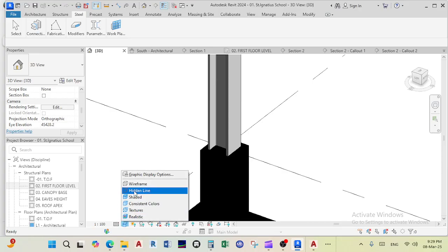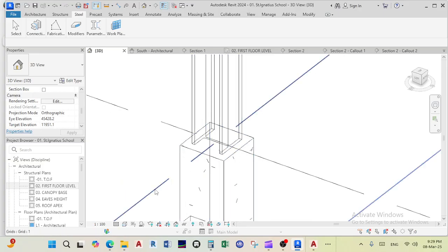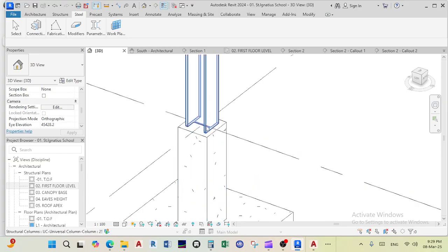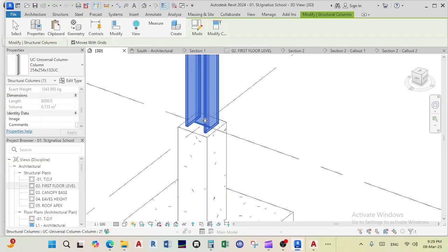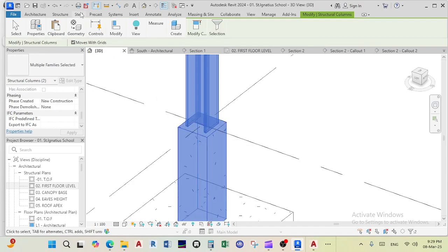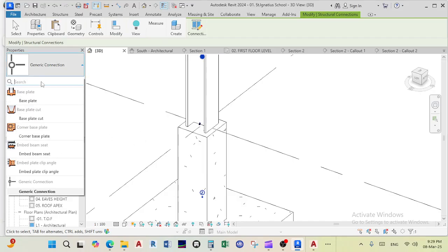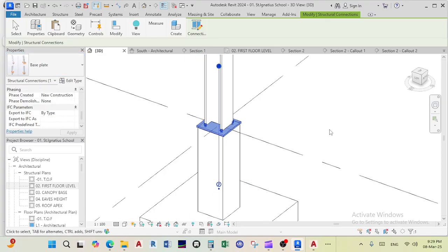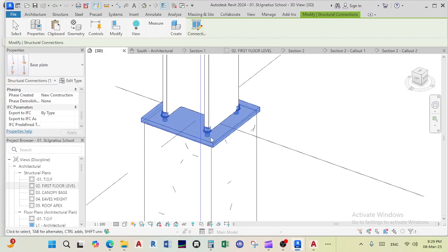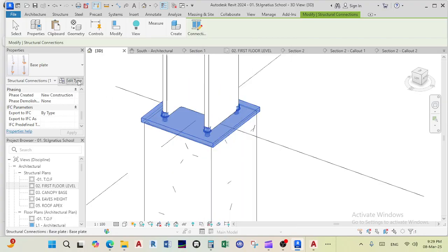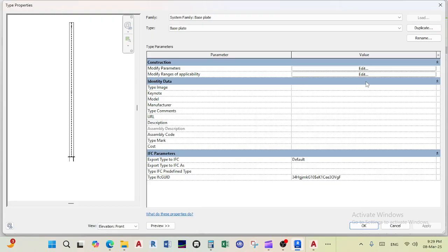Oh, I want to give it wireframe so that it's easy for hidden line. And then you click that, control, you click the stub, you go to your steel connection. This is basically just an end plate here, it's already here, base plate. And it comes, selects. You can change the type of hooks that you want, whether you want J hooks, according to edit parameters function here.